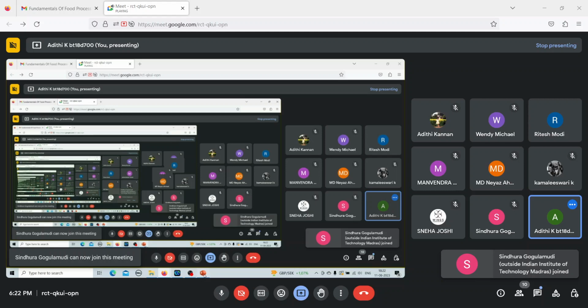So I have N0 equal to 10 power 12 and N as 1. My time is given as 5 seconds, and D is something we do not know. This D value is for 121 degrees Celsius, it is not for 140 degrees Celsius. So I am calculating what D is at 140 degrees Celsius. So log of 10 power 12 is basically 12. So 12 is equal to 5 by D. So D is equal to 5 by 12, which is equal to 0.416 second.